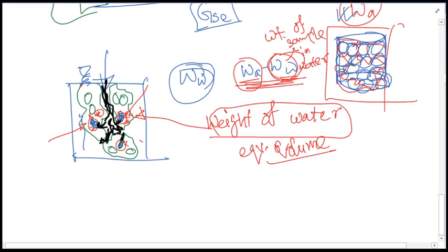So if we pick it up from the water, we will be drying the surface. Immediately after that, the surface will be totally dried by any means. If we immediately dry the surface, the water will still be within the permeable pores. It will have penetrated through that, and it will still remain within these pores.